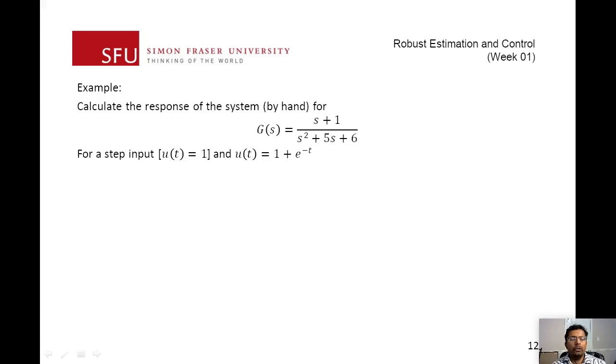So now we're going to do some exercise to appreciate the importance of Laplace transformation. We are given this transfer function of the system over here, and we're going to calculate the response to a step input, which is u equal to 1, as well as when the input is 1 plus e to the minus t.